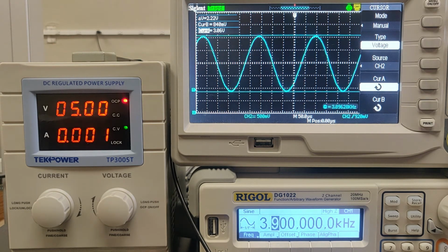In part D, we are asked to display a plot of all of those gain values at their corresponding cutoff frequencies. So you should have 6 data points, and the idea is to plot the gain on a logarithmic scale, the 20 log of our gain values, against the corresponding frequencies, also on a logarithmic scale, since it spans a very wide range of frequencies. But that's pretty much it for the data analysis part.